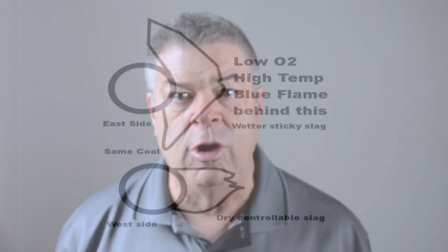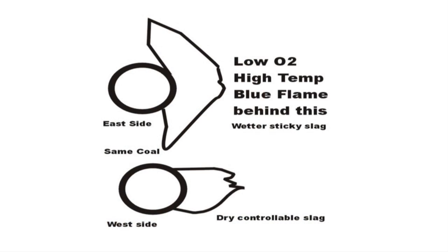Another factor in the combustion aspects of a boiler that seems to influence the slag formation in the upper furnace is the side with the lowest oxygen, or if you have an O2 split, you have to worry about the low oxygen side, particularly if some of the oxygen probes are getting below 2 or 1.5 or even 1% oxygen, and then they average up to some higher number, but you have a zone of low oxygen.